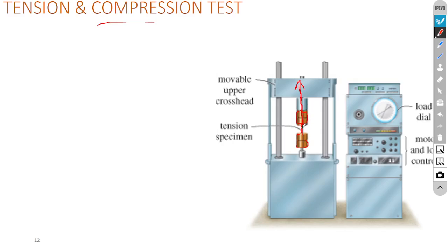Also the deformation is recorded between the selected points, and all the recorded values, the magnitude of the force and the corresponding deformation, are recorded within such a box. Within the box we have a computer, a microprocessor. It uses certain software to convert the measured values to what? To stress, to strain. And then stress and the corresponding strain values are plotted.